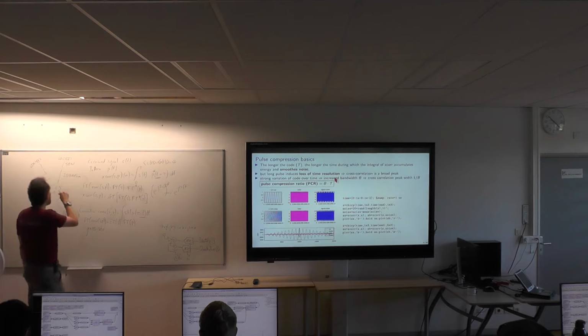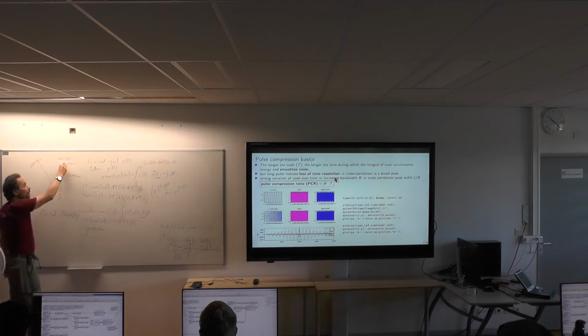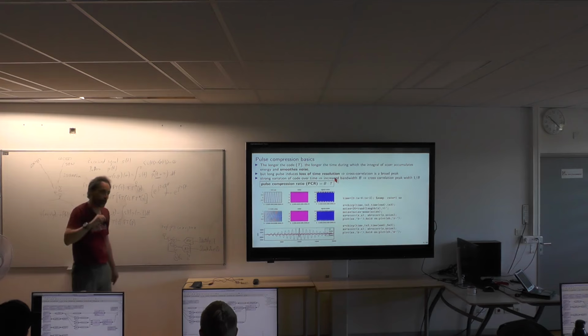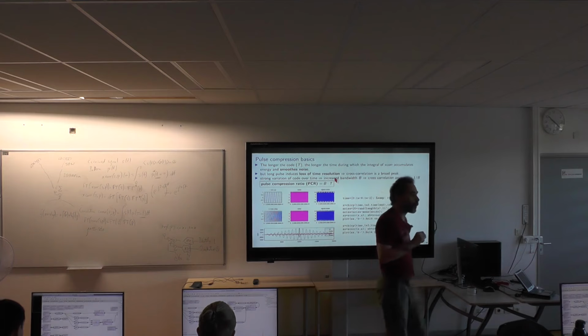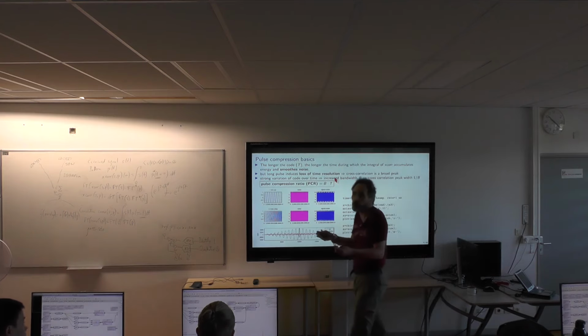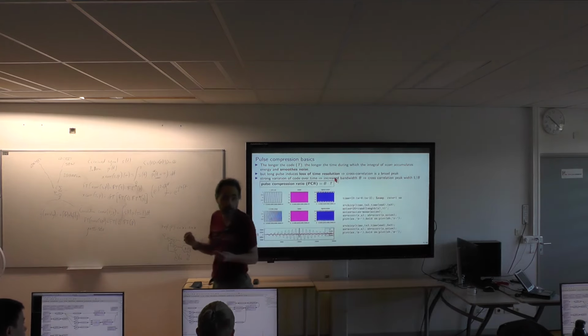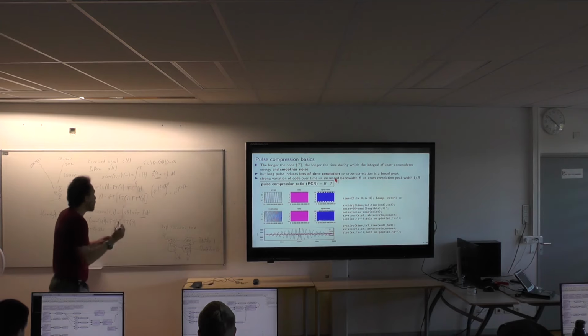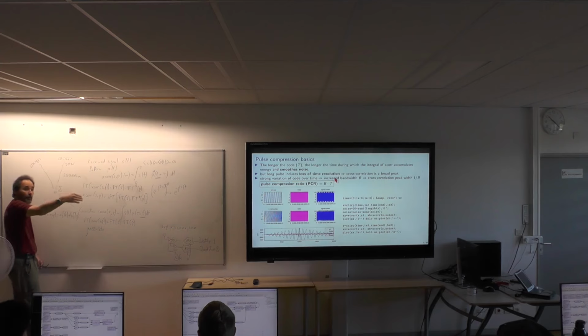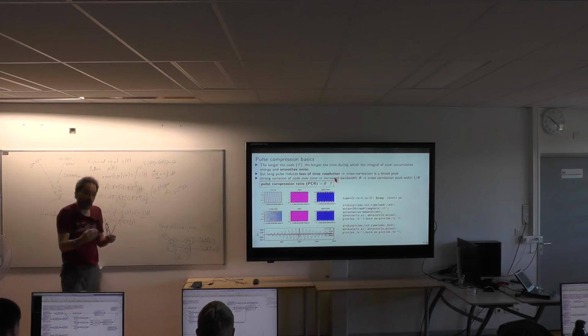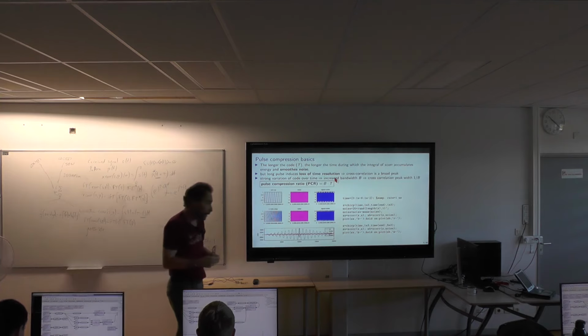So, of course, if this faint signal has propagated all this way to your receiver, this signal will be very weak. Actually, it's 10 decibel below terminal noise. What would you do if you want to extract a signal from noise? What is the mathematical operation you would use to get rid of noise? Averaging. So what we would do is say, let's average out these multiple time evolution copies of a signal, so noise slowly lowers until the signal comes out.